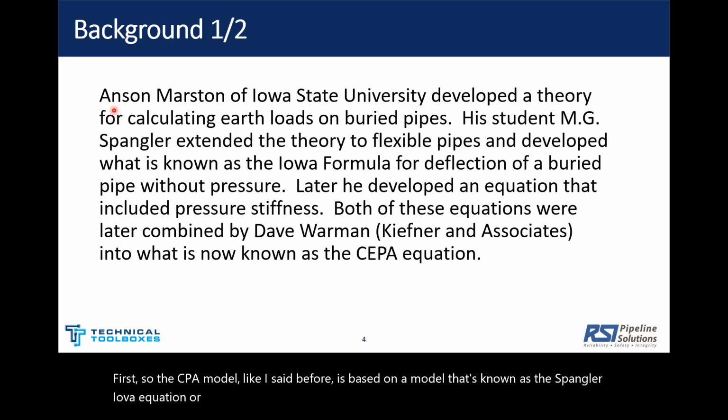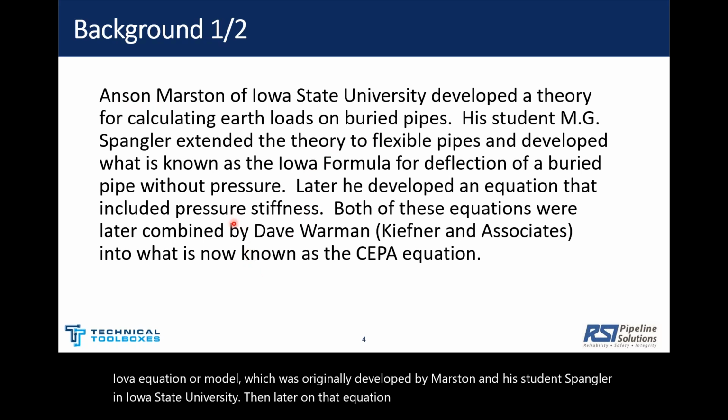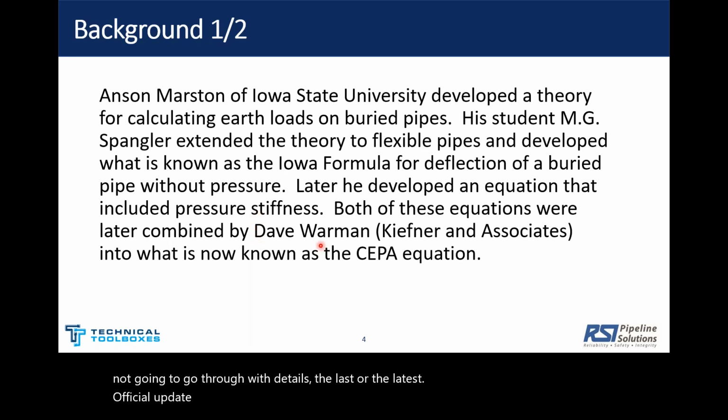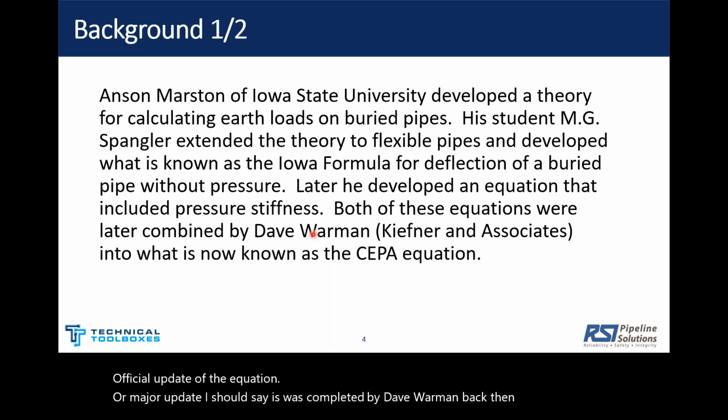The CEPA model, like I said before, is based on the Spangler-Iowa equation or model, which was originally developed by Marston and his student Spangler at Iowa State University. Later on, that equation was modified multiple times, which I'm not going to go through in detail. The latest major update of the equation was completed by Dave Worman, back then with Kiefner and Associates.